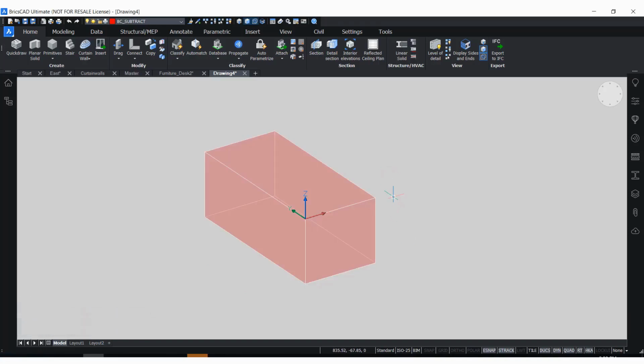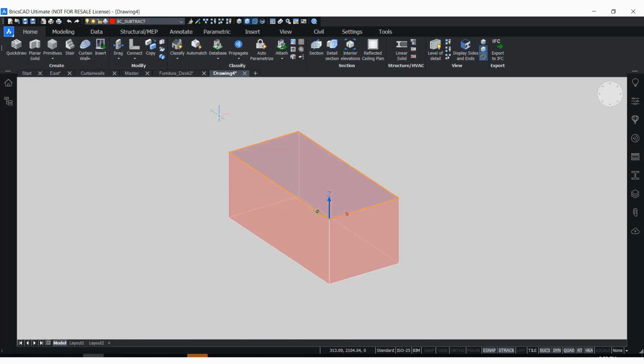What is important is that you have to keep in mind, right now what we're building is a window, and most of my walls are not gonna be bigger than, what, 40 centimeters? So your subtract just has to be thicker than the thickness of your wall, because the subtract is going to be what's going to create the opening in those walls.